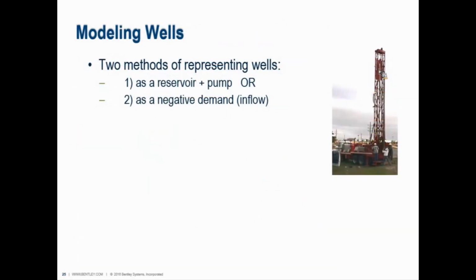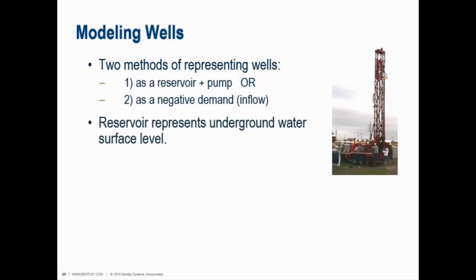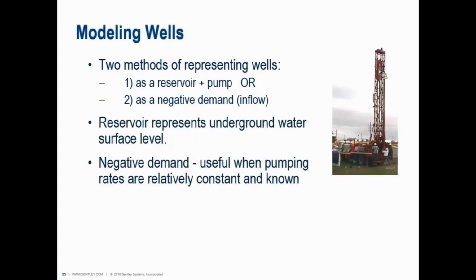Okay, modeling wells really quickly. Yes, we can model wells. There is not a well element in WaterCAD and WaterGEMS. However, the way we get around that is using a reservoir and a pump, or a negative demand. I prefer the reservoir and the pump because then we can actually model the true performance of the well pump.